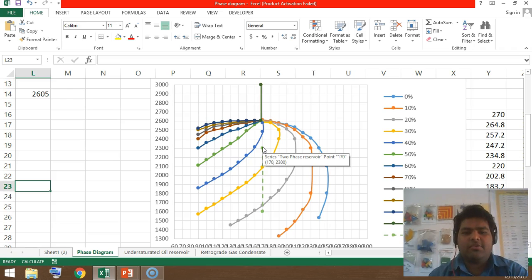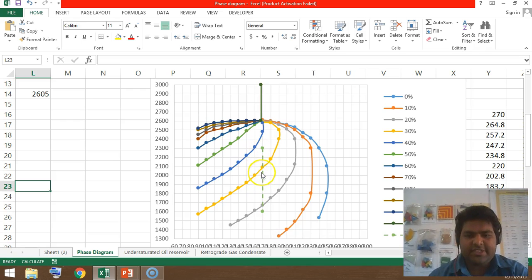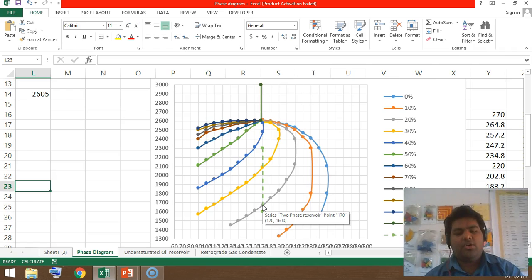So the reservoir fluid will be in two phases right from the beginning itself. The reservoir fluid would be part liquid and part gas. So as production starts and the pressure is reduced, the liquid percentage will decrease. Like initially it was 30% at this point, and then at this point it will be 20%. So the liquid percentage would be decreasing, in the reservoir as well as in the fluid produced at the surface. So again at the surface we will get partly liquid, partly gas, but the flow of gas will be increasing and the flow of oil will be decreasing.